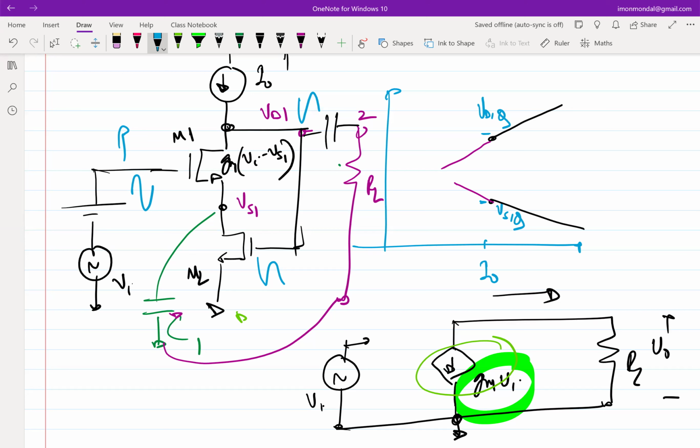It is going to change. But is it going to affect RL, I mean, the voltage across RL? Where will that incremental current of M2 go into? Through C1, right? So the incremental current of M2 will essentially be circulating between this drain and the source. Okay. So the only purpose of M2 was to give the bias. It was not supposed to affect our main operation. So C1 also helps in doing that.